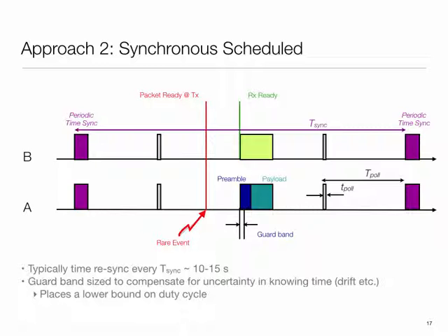So what may happen is, let's say at some time t, the master sends out this packet. The nodes were up, they listened to it, they adjusted their clock, and then they arrange to wake up the next time the master is going to send the packet, plus some margin for error that may have built up during that time. By doing that margining, we make sure that we wake up and again readjust the clock, and things go on from there. Otherwise, if a rare event happens, then at the next transmission opportunity we know that both parties are going to be up. Again, we can budget for some clock drift, and then we go ahead and shoot out the packet.